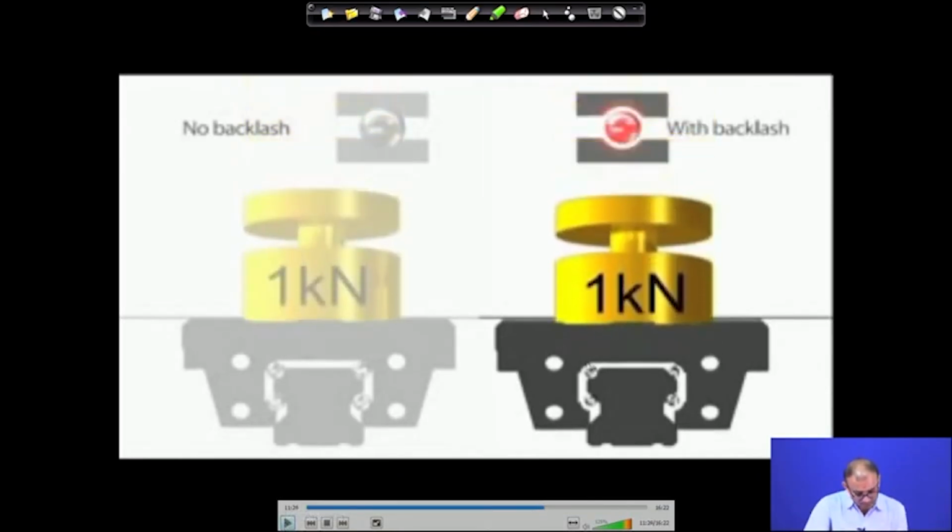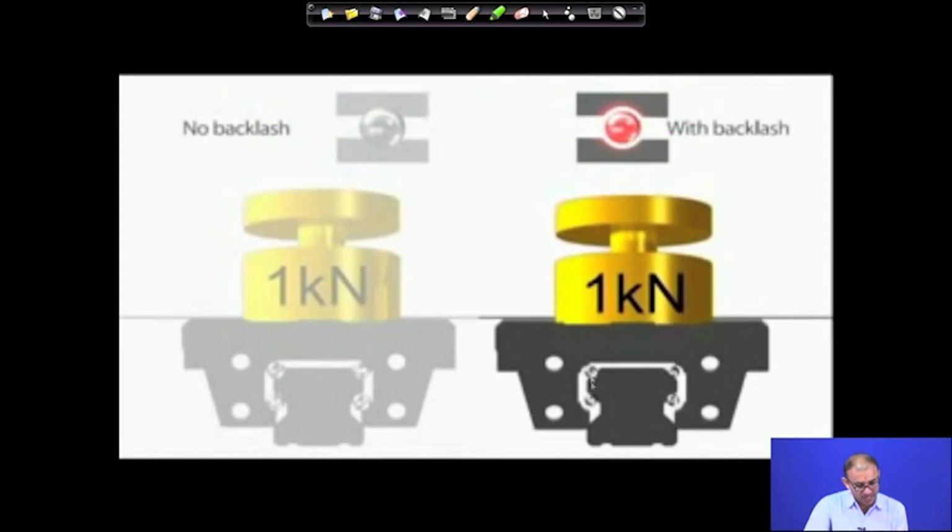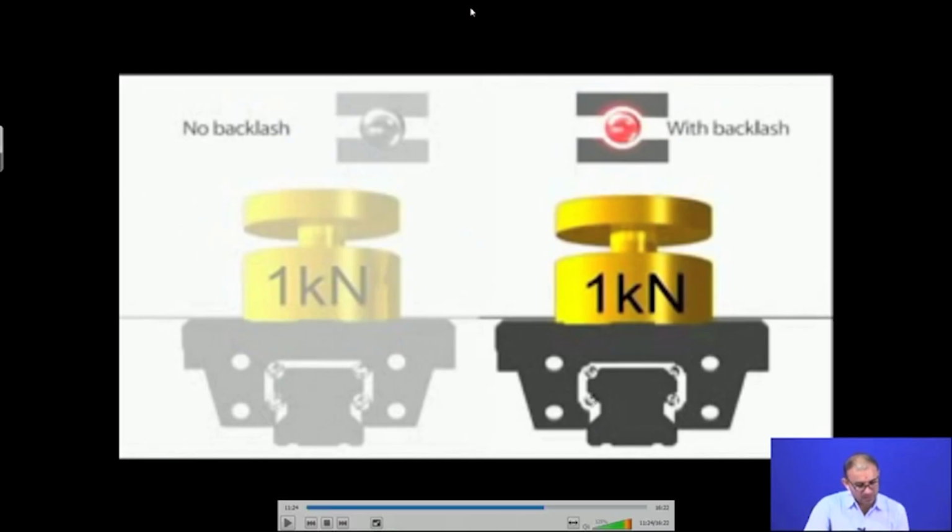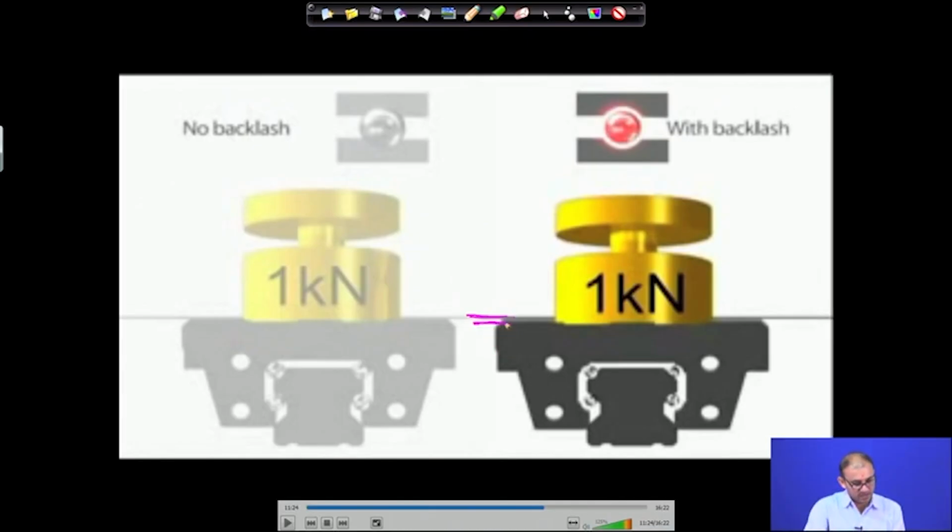Now, under the backlash, what is going to happen is that when you add a 1 kg load, because we have backlash, your whole thing will go down. This is your reference surface, and now your reference surface is shifted a little bit down. So now your whole machining goes the wrong way. Consider again the same example: you want to cut a slot, and the depth is 50 micron, and because of this problem your workpiece will go down.